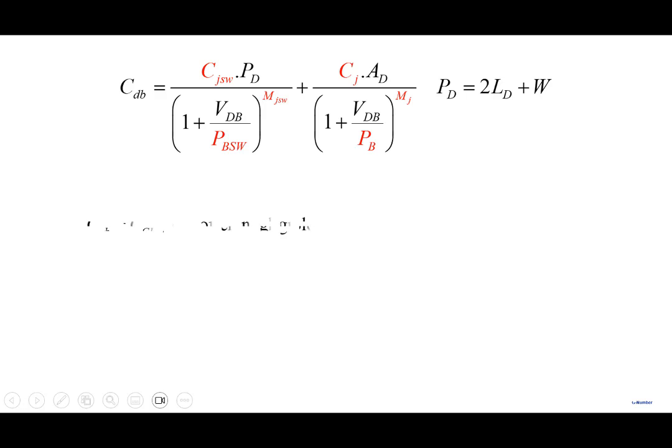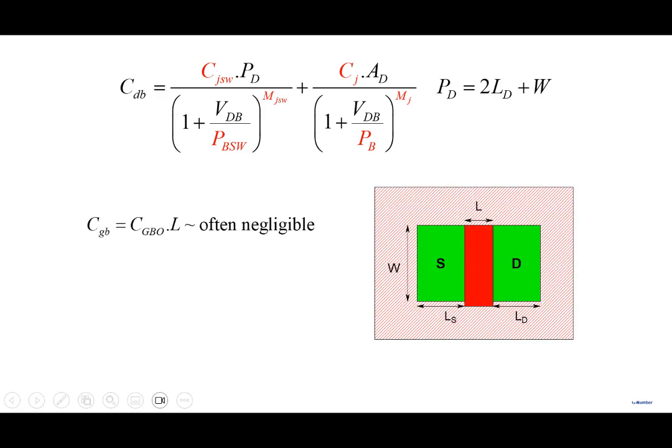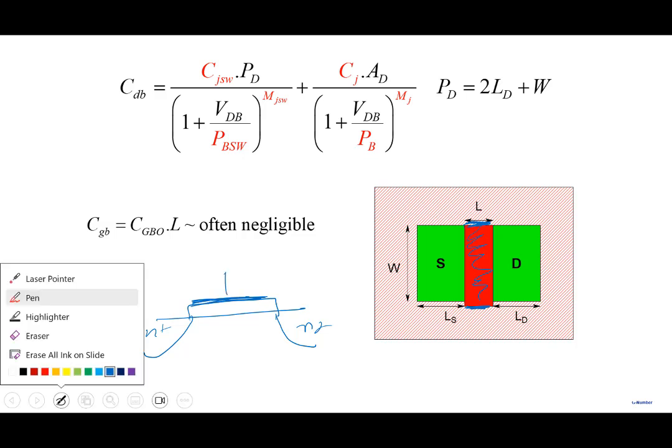The only thing that is left is an overlap capacitance along the fringe here, along this side and this side here. So there is no area component because no field lines are penetrating. Once the inversion layer forms, the inversion layer acts as a shield. It doesn't allow any field lines to go through. Right? So note that you have N plus, and before you form the inversion layer, you have the depletion width.